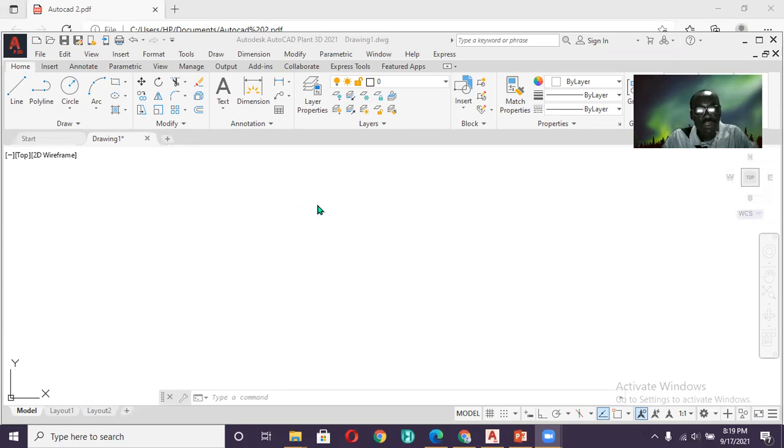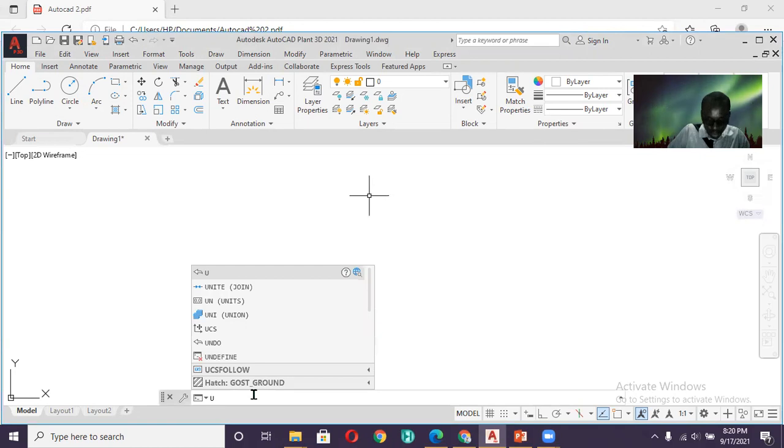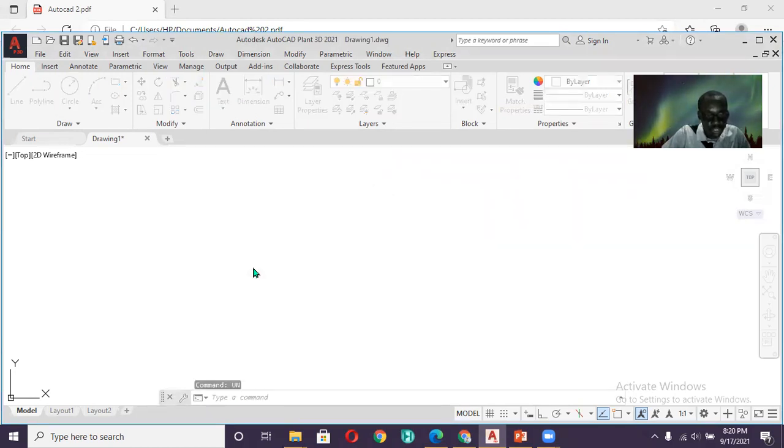First and foremost, our menu bar is displayed, our ribbon is displayed. So we're going to set our units. I've already taught you in the previous video how to set your unit. You go ahead to the command window, type UN, choose unit.